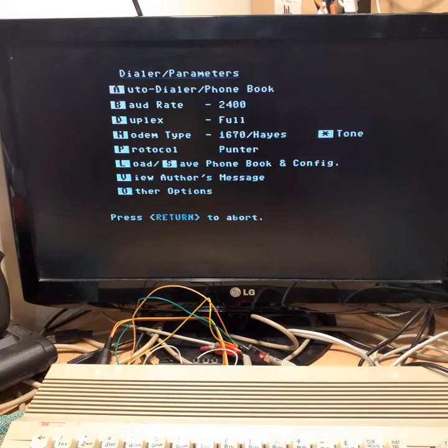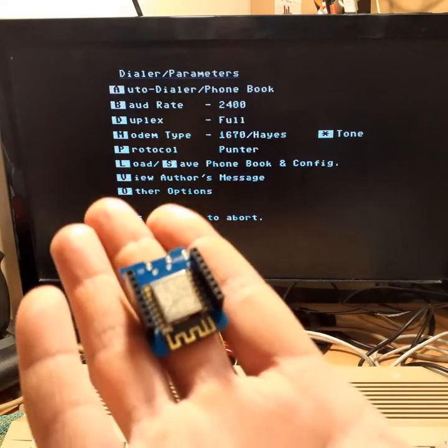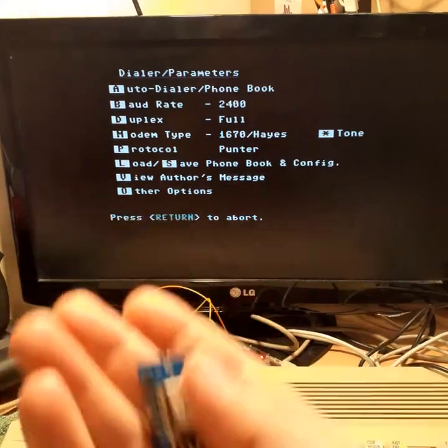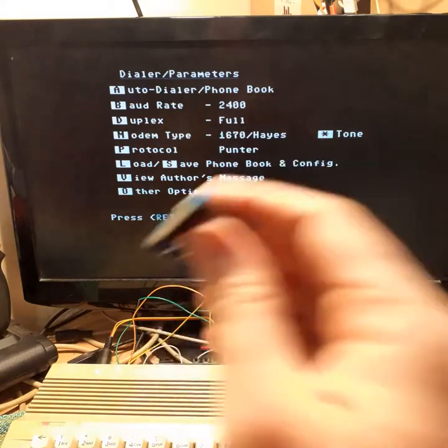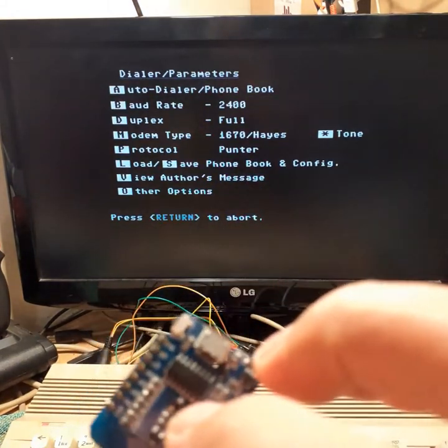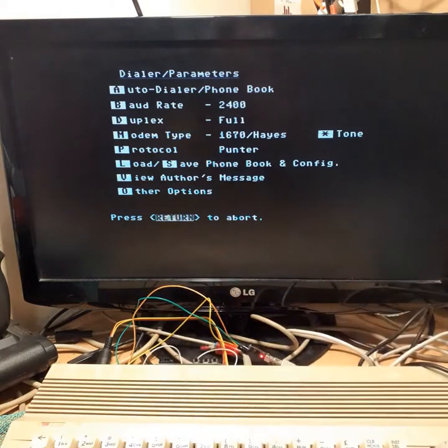Also in the last couple of years there are Wi-Fi modules available for Commodore 64, and what they use is one of these, that's ESP8266 or ESP32. Again, TTL connection directly to Commodore 64 works just great. The only downside of the Commodore TTL connection is actually the speed. So it was very slow back then, and especially very slow today.